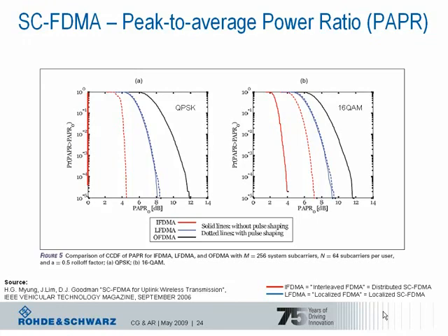As we can see, the crest factor for OFDM is constant at around 12 dB, which is comparable to WiMAX, and it is independent from the modulation scheme and the used filter. This is different for single carrier FDMA, especially for interleaved FDMA. For localized FDMA, which is the blue line and the mode used in LTE, the peak to average power ratio is, in case of QPSK modulation, around 8 dB and therefore 3 dB lower than OFDMA. For 16-QAM the difference is just around 2 dB.